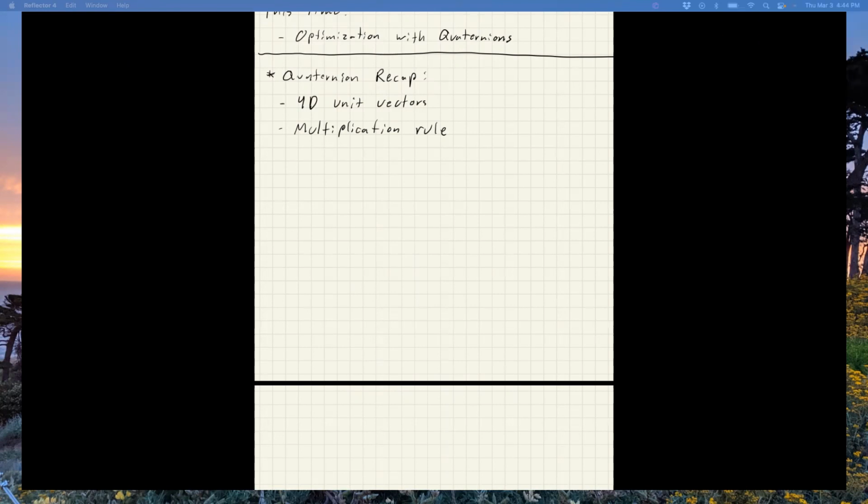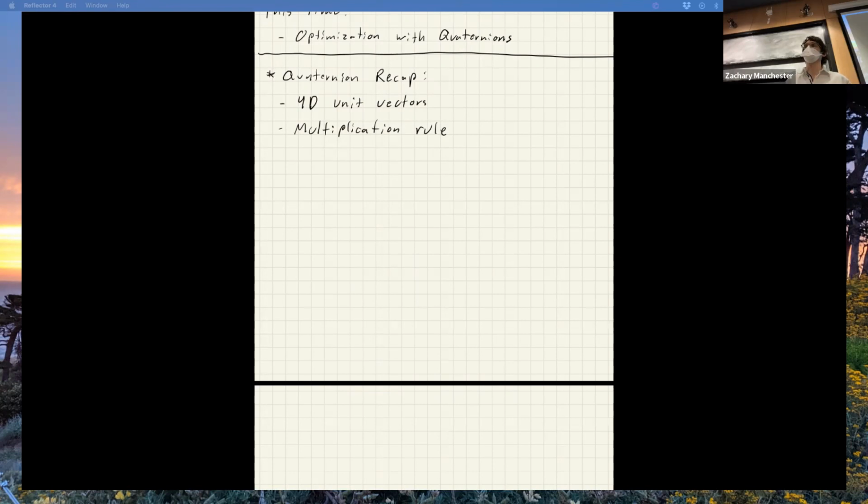Yeah, I had a quick question. Last time you mentioned that there's a formula for quaternion velocity. Is there a nice way to express acceleration in quaternions, or do we not need to do that for this type of problem? Yeah, you don't need to do that. For velocity and acceleration, you're going to use the standard angular velocity vector, and then its derivative for angular acceleration. The quaternion stuff you really just want for representing the pose or configuration.